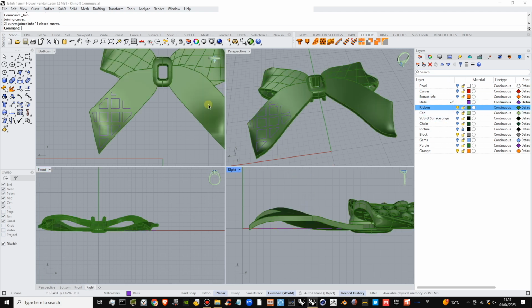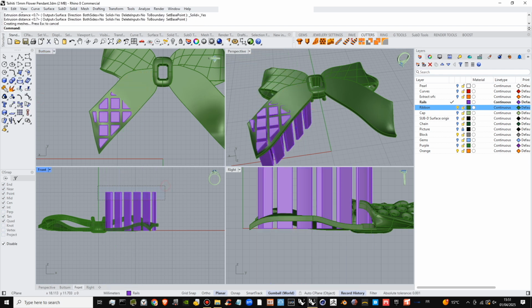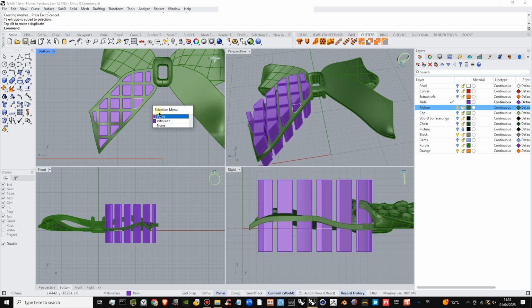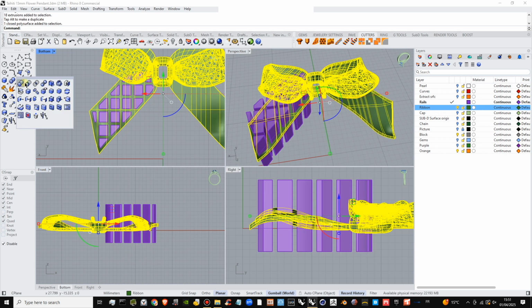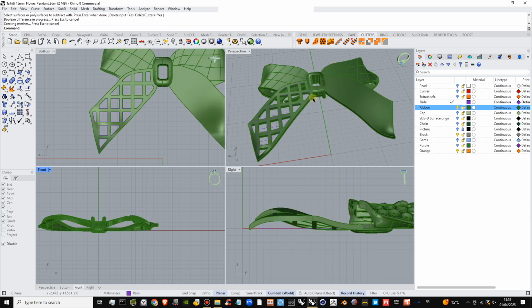And let's open our ribbon, and this is where I'm just going to take that pattern and I'm going to extrude it, lower that down, and I'm literally just going to bang that out of the bottom. Just going to boolean that straight out. There we go.